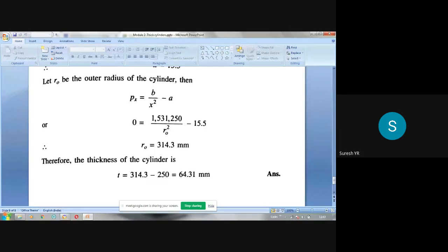Bending moment and shear force: please go through the mechanics of support reactions. Three equilibrium equations are there. One is sigma Fx = 0, another is sigma Fy = 0, third one is sigma M = 0. Sigma Fx = 0, in most of the cases, will not be used. Mainly in the case of beams, we are not using sigma Fx = 0, only in hinged beams. Whereas sigma Fy = 0, the sum of all the vertical forces including reactions, should be equal to 0.